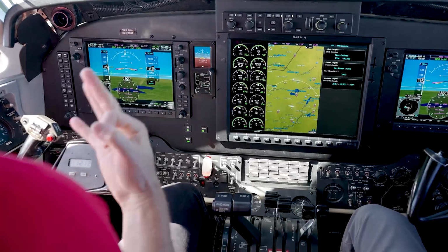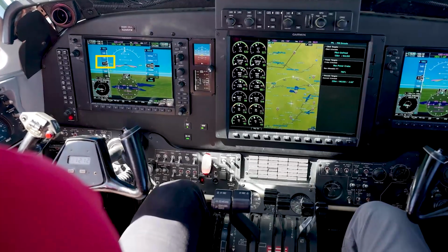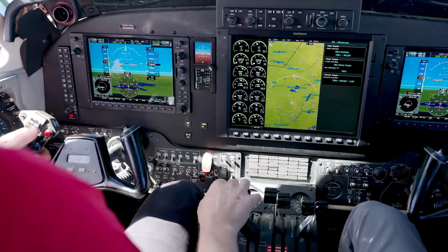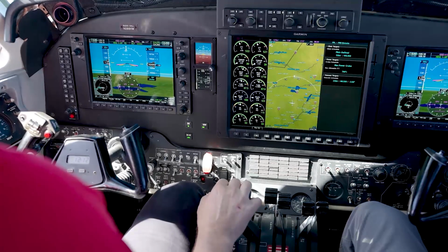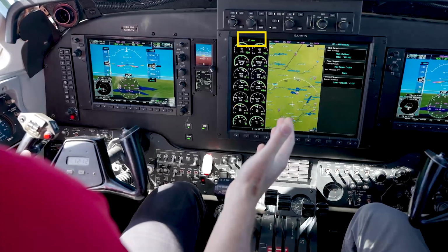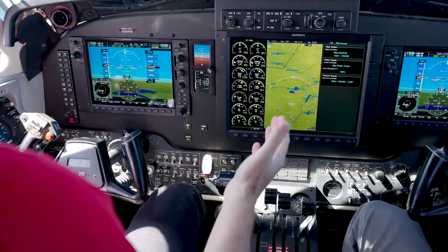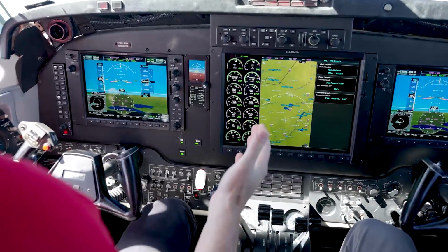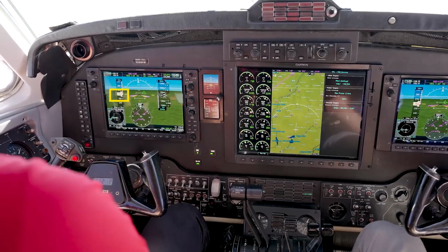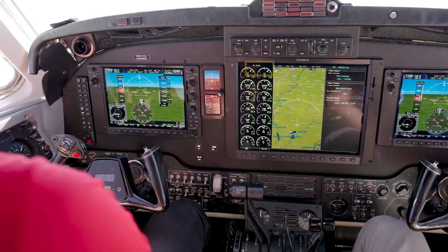Similar to the electronic stability protection of the Garmin Autopilot, the autothrottle has protection modes to assist with safe and efficient operation. The autothrottle will engage to prevent over and underspeed conditions by moving the throttles accordingly. This will occur regardless of whether or not the autothrottle is engaged. In an underspeed condition, the autothrottle will increase power to increase airspeed. ATV-min will display in the autothrottle mode annunciator when this protection is active. In an overspeed condition, the autothrottle will reduce power to slow the aircraft and annunciate ATV max.